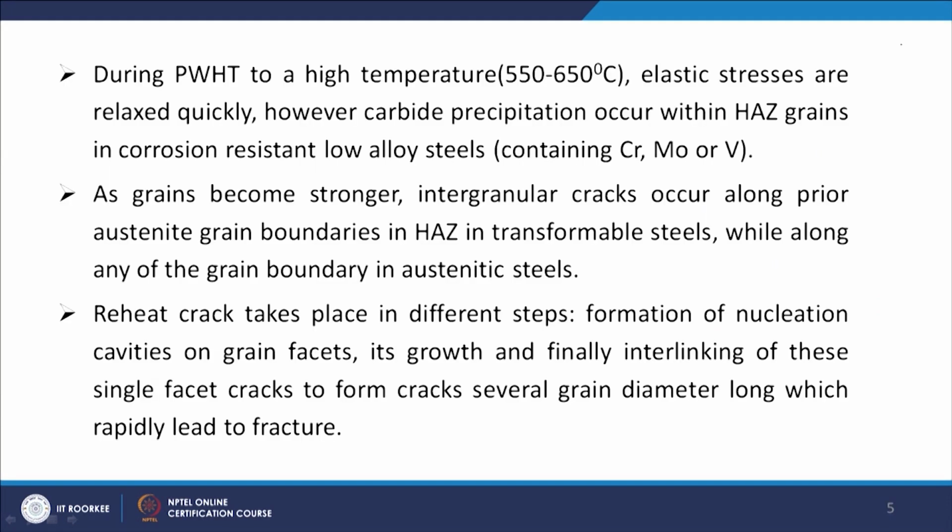When we do post weld heat treatment at a higher temperature, we normally do it in the range of 550 to 650 degrees centigrade. That basically quickly relieves the elastic stresses.